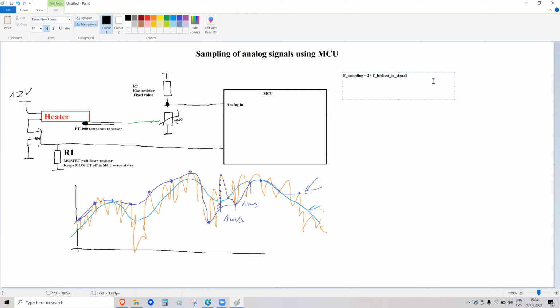What you would do is make a decision that you want to, for example, sample at something like maybe 10 samples per second, and then you use a low pass filter to remove the higher frequencies. And the low pass filter will be such that it guarantees that the output frequency of that filter is at least 2 times lower than your sampling rate.